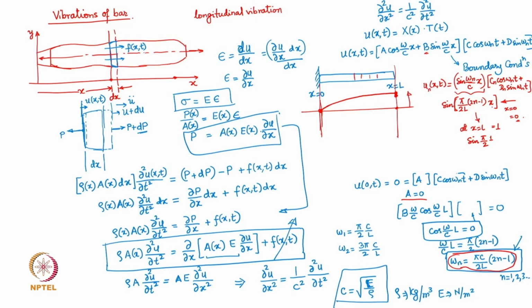It's just a way of showing that this particular element is going to be stretching along the longitudinal direction by a value equal to this, in relation to a unit value at the free end. That's what the mode shape is all about, right? You show the relative displacements of each element of the vibratory system with respect to some reference displacement of one reference element in the system. So that's basically the first mode shape.